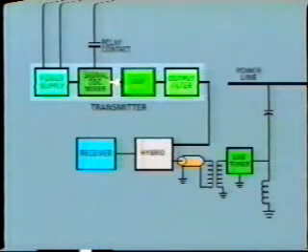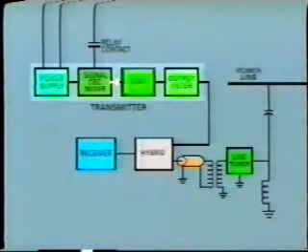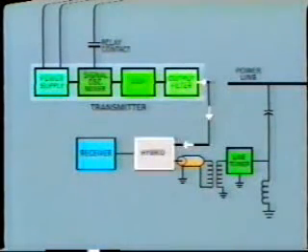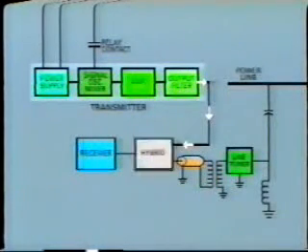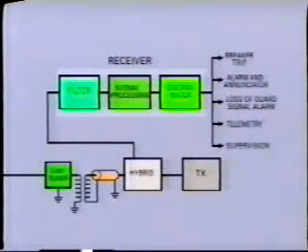The next basic stage is to pass the oscillator signal through an amplifier in order to boost the power to, say, 10 watts, sufficient for transmission to the receiver at the far end of the line. The boosted signal will then pass through the output filter, which is tuned for the specified operating frequency. Finally, it will pass through a hybrid unit if fitted, and from here, via the coaxial cable, to the line coupling equipment.